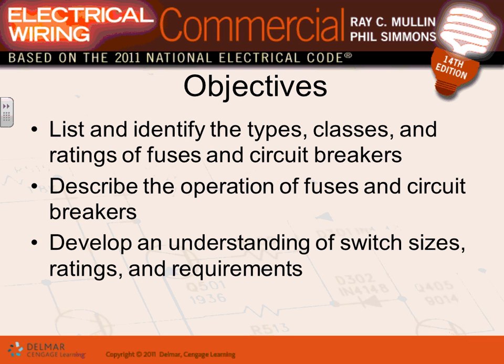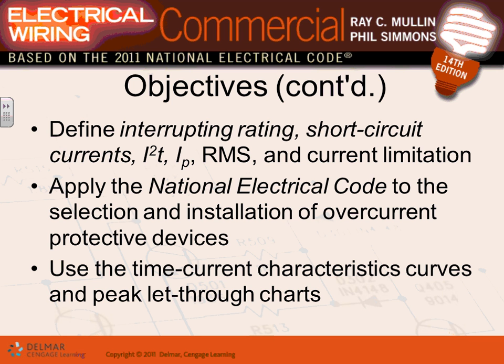Again, you can capture as much of this information as you can, but be aware, every circuit that you guys have done with me in Revit, as well as in the schedules, you have to have an overcurrent protection device for it. Understanding of switch sizes, rating. Every time you have a fuse, you have to have a disconnect with it, for the most part, so we can isolate that fuse. So we'll talk about the rating of the disconnects.